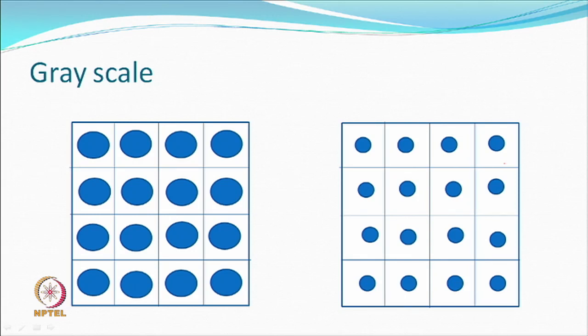Another way of creating a different grayscale is that you have a lighter color actually, that the concentration of the dye in the ink is less. That also is possible. It is still called the magenta, but it may be lower concentration magenta. So, your strategy could be either you change the drop size and get the appearance because of the ground, or you actually use an ink which has a concentration which is less.